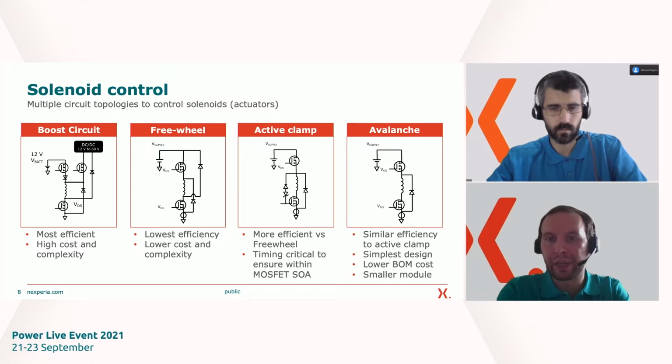Again, we're driving a solenoid here. What happens when the energy turns off is the voltage across the inductor will increase to a certain point that forces the Zener to break down, and this will turn the MOSFET, as you can see here, between the across the high side of the inductor and the gate of the MOSFET. It will exceed the switch on voltage and turn the MOSFET back on.